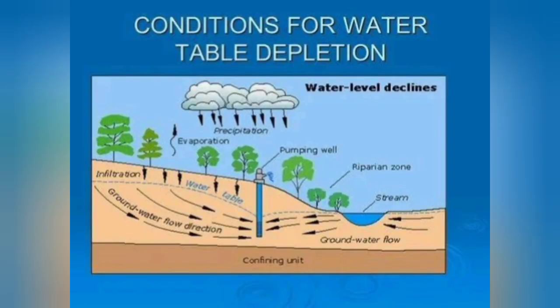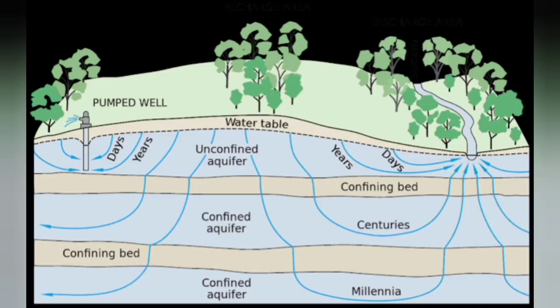So a few pieces of information are required for that: the quantity that may be diverted for artificial recharge, the time for which the source water will be available, the quality of source water and the pretreatment required, and the conveyance system required to bring the water to the recharge site. Hydrological studies are undertaken to work out surplus monsoon runoff which can be harnessed as source water for artificial recharge.